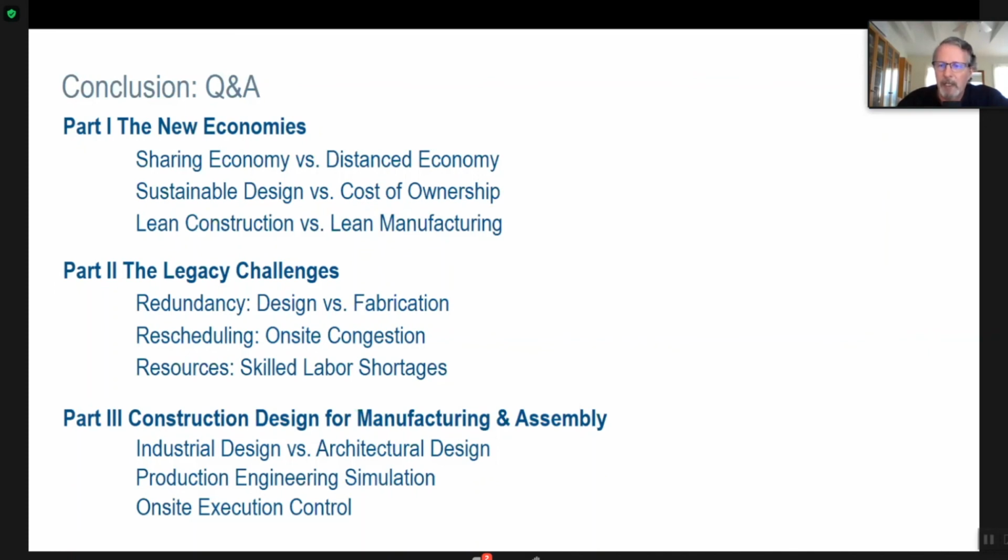is problematic. I think that the decision for more panelization or more volumetric is based on the labor. If you think of a bathroom pod as a classic example, every trade goes in. You send in the framers, you send in the plumbers, you have to put a fan in the ceiling, says an HVAC guy. You've got the electrical guys, you've got tiling, you've got every trade going into a tiny space. So what that tells me is it's worth shipping the air.